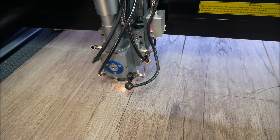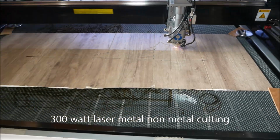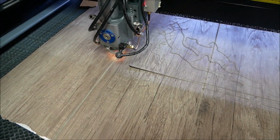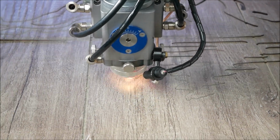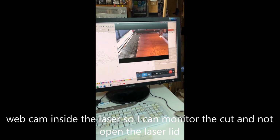This barn board really cuts well, makes a nice fine cut. I'm using a 300 watt CO2 laser. It cuts metal, non-metal. I also use about 28 psi of air. That's what makes the cut so fine. I like using that barn board panel because you don't have to paint it or spray it or protect it. You just cut it and your work is done.